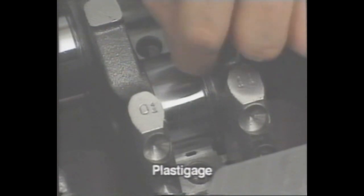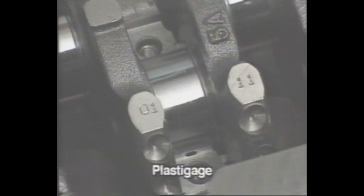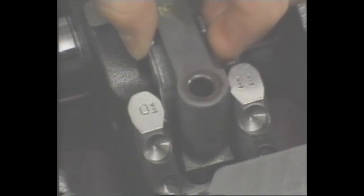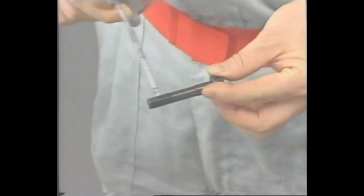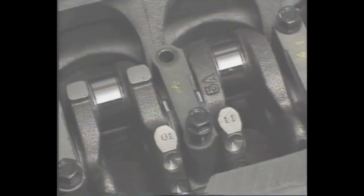After cleaning the journal bearing with waste cloth, set a piece of plastic gauge axially on the crank journal and install the bearing cap. Apply a thin coat of engine oil to the threads and bearing surface of each bolt. Do not turn the crankshaft during measurement.